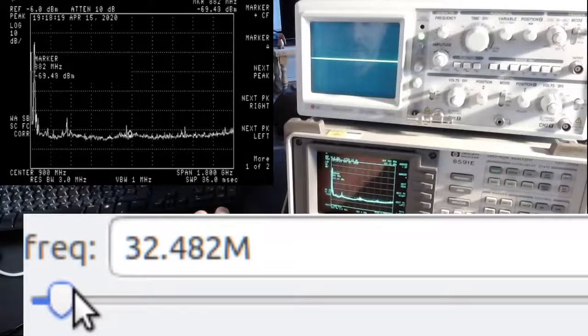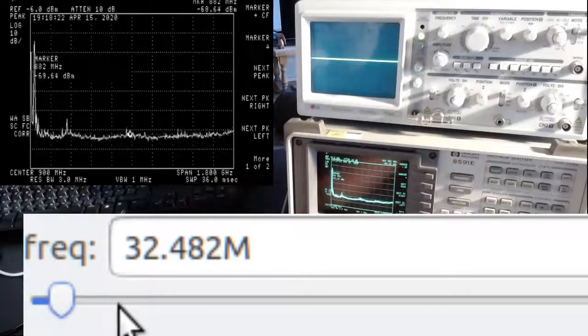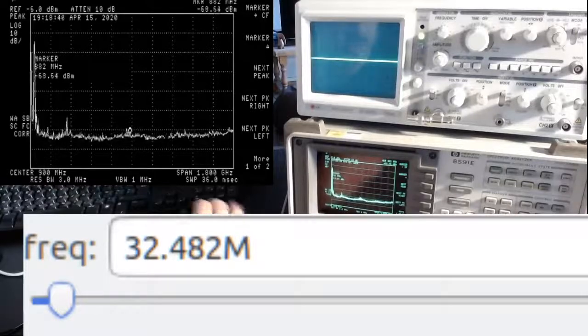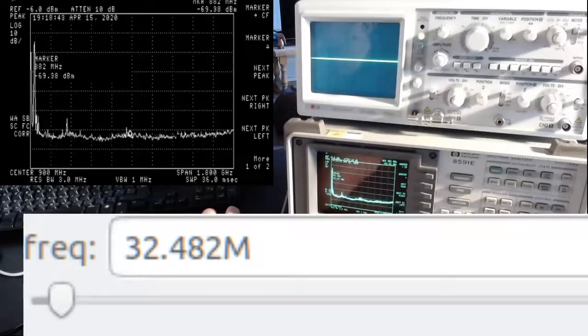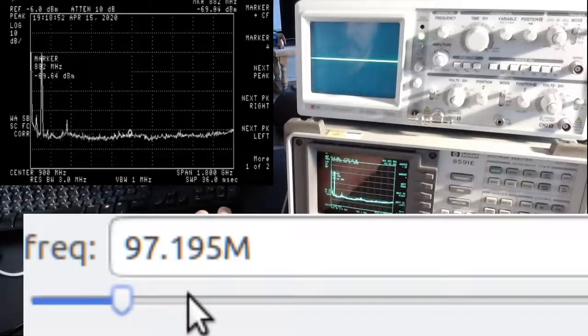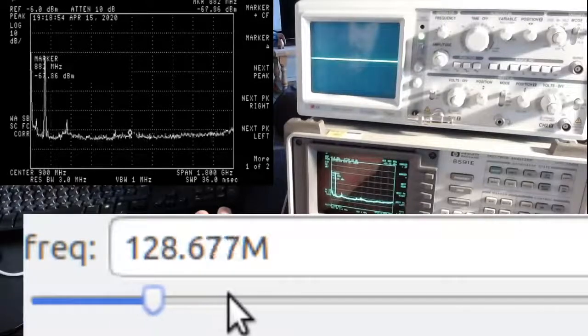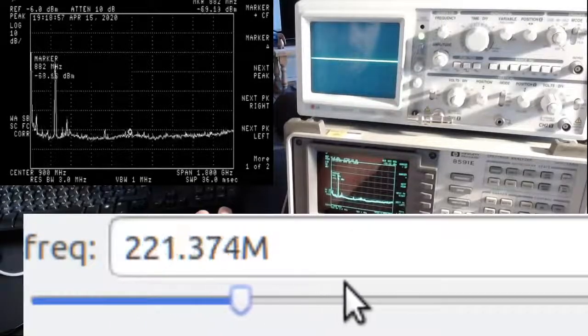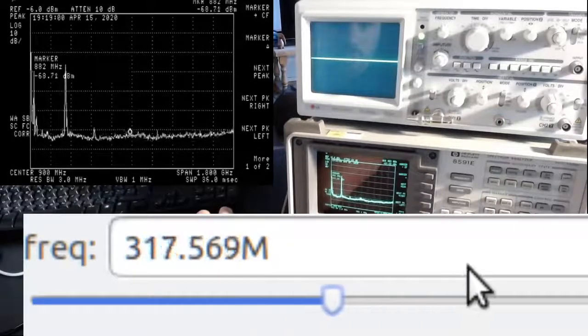So again, just visually here, this is just a first test. I don't want to go into any details here. I just want to have a very first look. I want to see if we can claim that the HackRF outputs the main frequency, and then all the spurious emissions are at the very least minus 30 dBc down. So let me just again sweep across the spectrum. To check if this is the case, 30 dB, remember, means 3 divisions. So it looks like here maybe, yes, so this is still probably true.